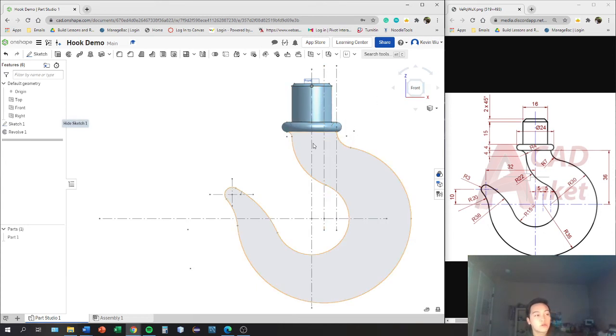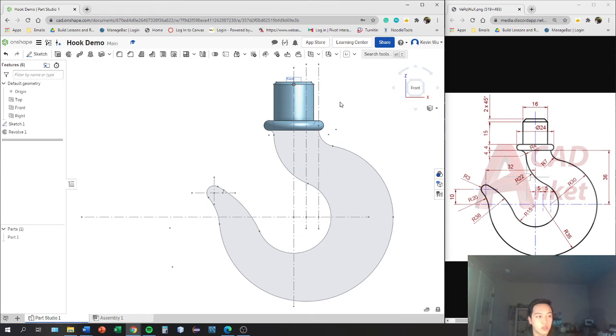Another thing to note is that with this, you can't actually use a sweep function. A good example of a sweep would be a paperclip, because if you were to stretch out the whole paperclip to make it flat, it would be the same diameter throughout, for example, 0.01 centimeters or something like that. But in this case, because the hook has different diameters, notice how it gets smaller and then bigger and then smaller. You can't really create a sweep out of that.